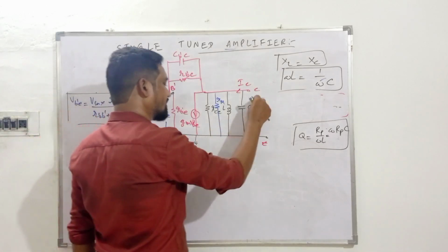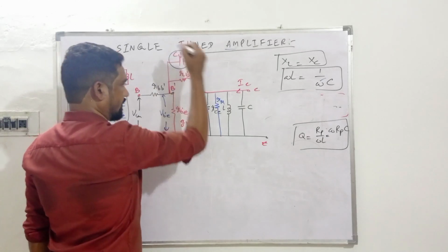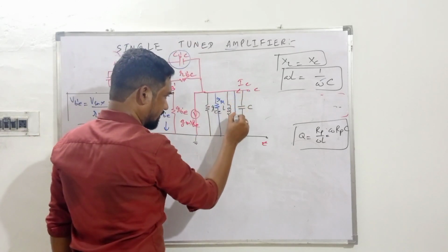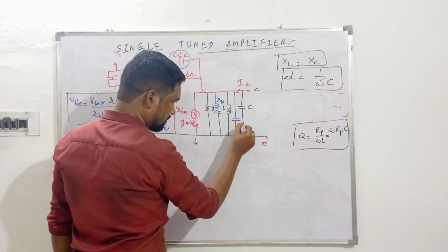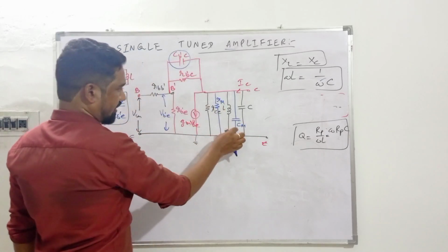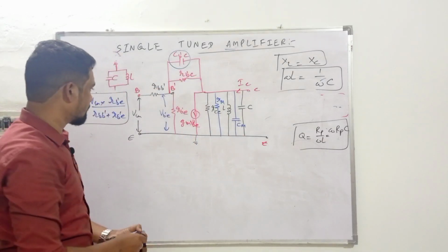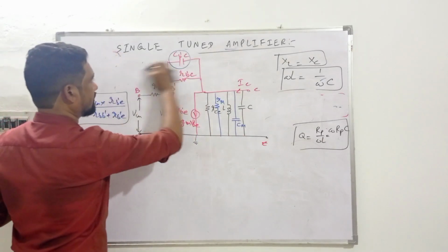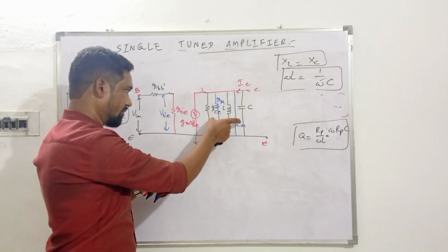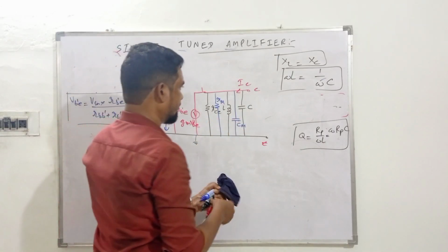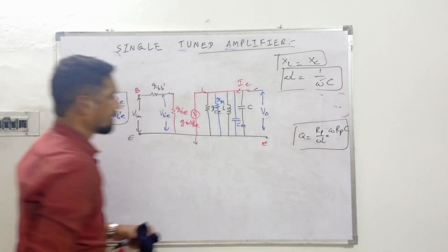Not only this resistance, some other resistances also come in between. Please check it. And even the capacitor can be split, and that is Cm, saying that that capacitance came into the picture with Miller's reduction. So this is also done. We don't need this anymore. For the analysis we need only the output, where that V naught will be appearing over here.